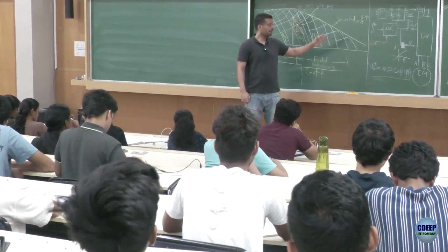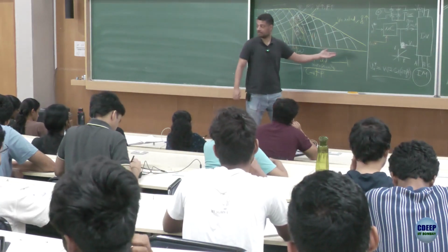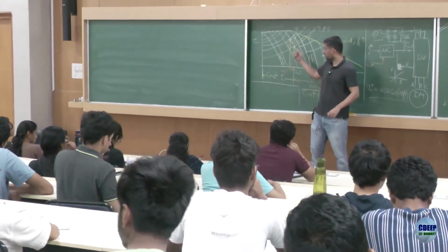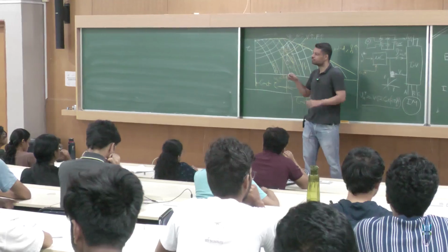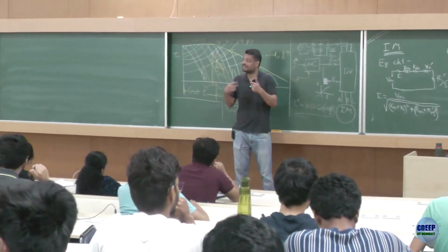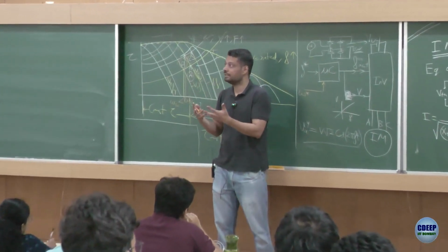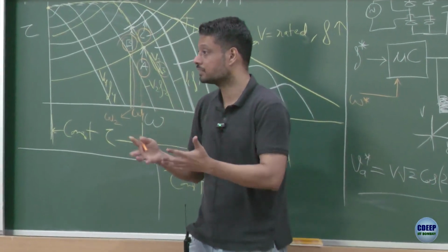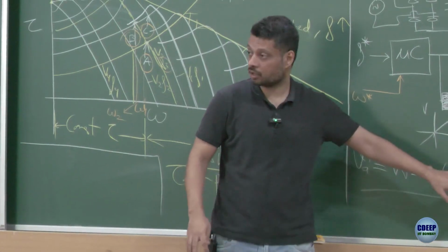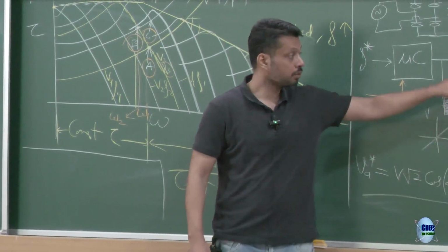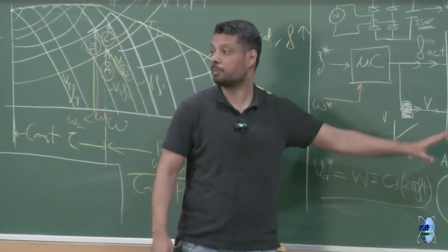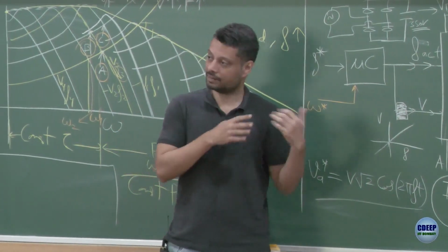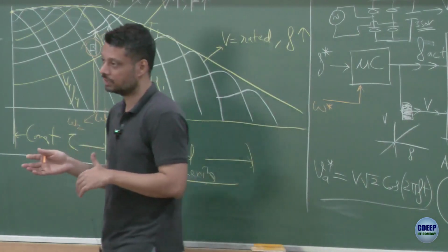If you look at it, in reality, if you have to implement it, you have to do a modeling of the induction motor, which by the way we have done. The one which we have done is more of a steady state model, but in reality, if the transient response matters a lot to you, then you would do a transient model of the induction motor also. You would do the modeling of the inverter; this would be your plant, this would be your controller. So everything you have learned there fits in here, and whatever you learn here fits there also, right?